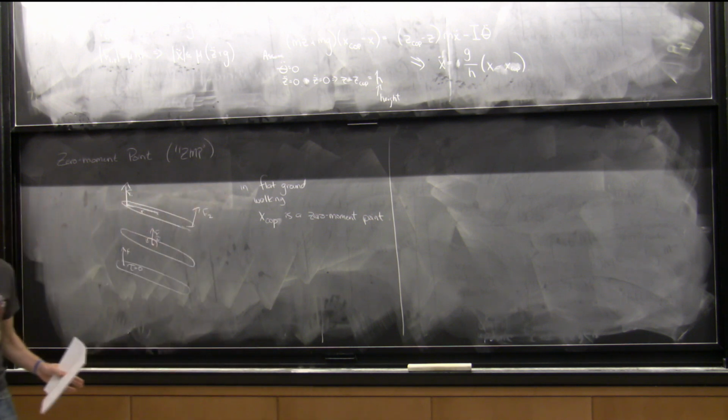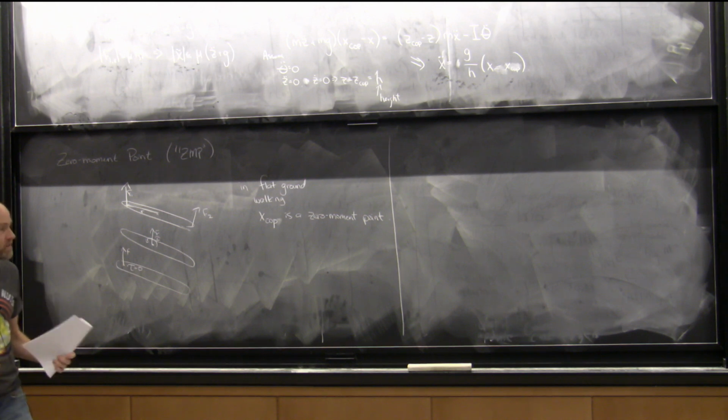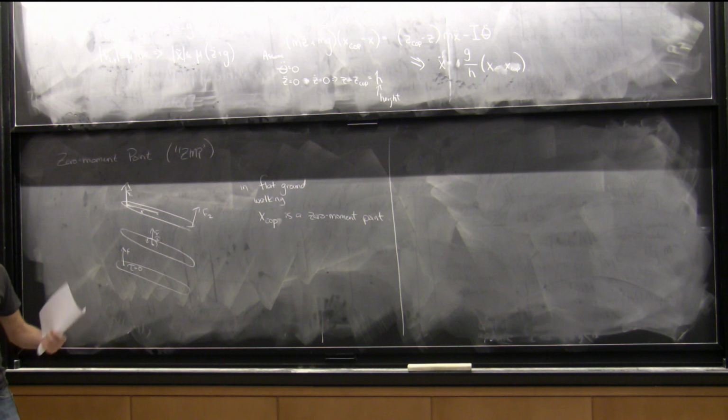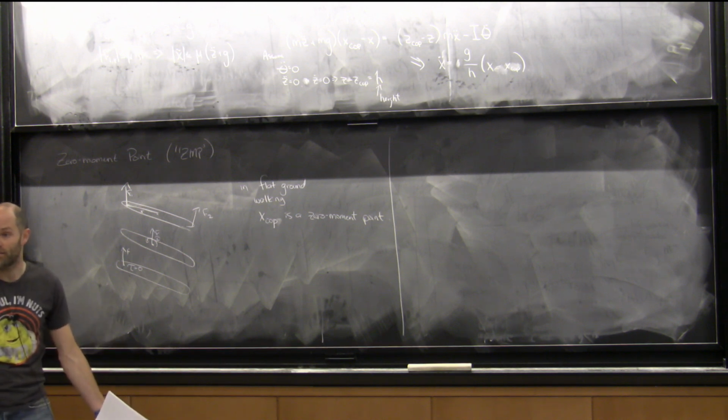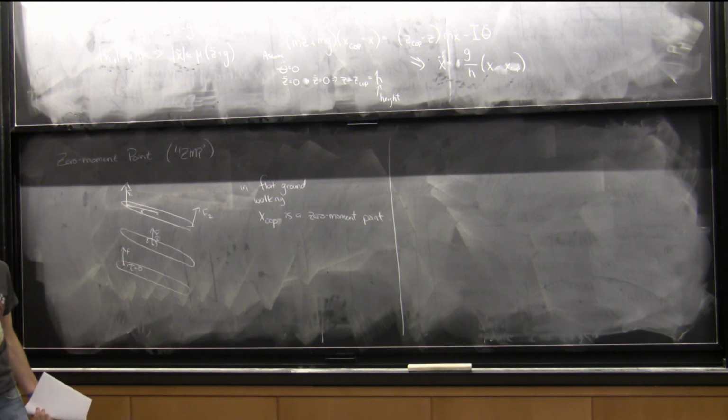As a second pass, you're going to then program your center of pressure and center of mass to be consistent with those footstep plans. And then maybe the last pass is you fill in all the details to try to make your legs actually achieve that center of pressure or center of mass.